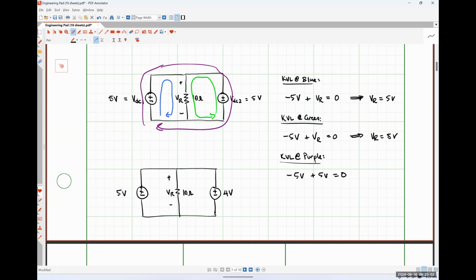So the voltage drop across a wire in this case would be somewhere in the ballpark of 1 volt. If we had 1 volt drop across a wire with a milliohm resistance, the current flowing through it would be incredibly high. And effectively, the wire is just going to get really hot and you're probably going to catch something on fire.